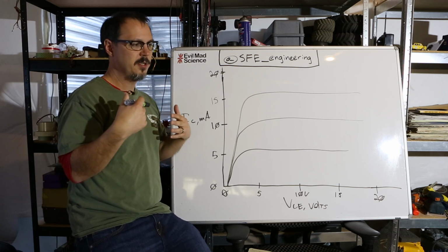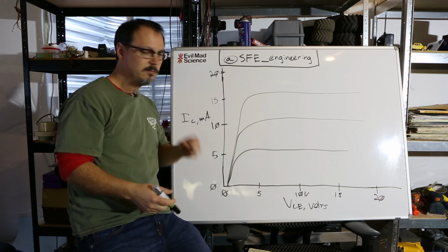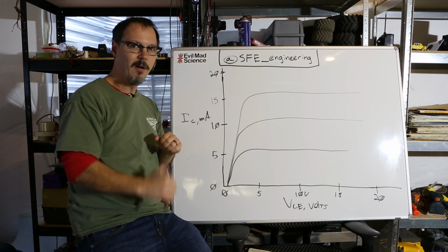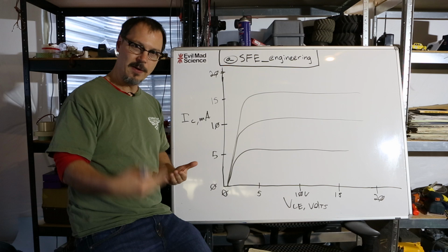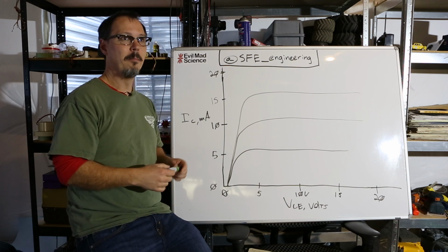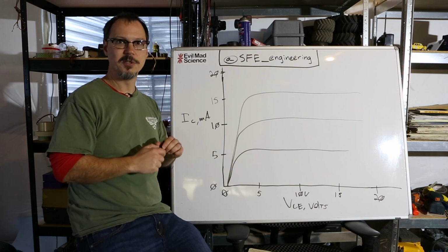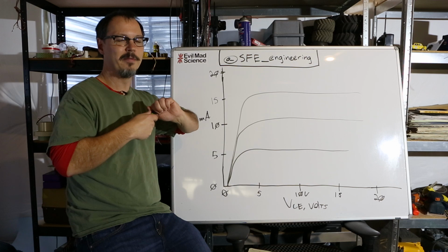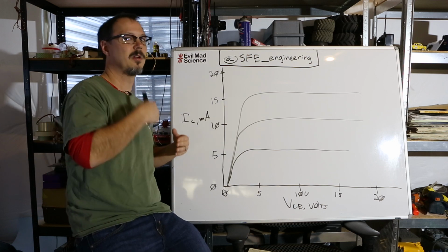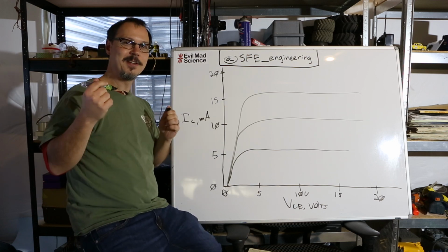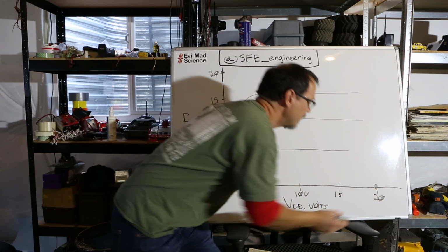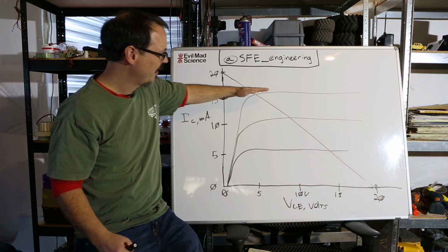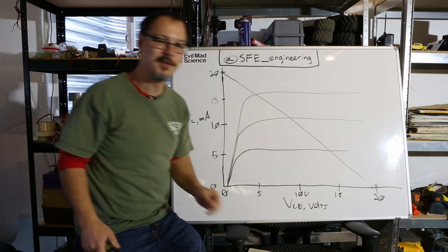When you turn the transistor off all the way, so you've got that valve cranked down all the way and you're trying not to pass any current through it, it's going to have the maximum amount of voltage across it. Probably the supply voltage. If you can turn that valve off enough, you're going to get the supply voltage from collector to emitter. And in my case, conveniently enough, it happens to be 20 volts. The different values of base current cross that line at different places.